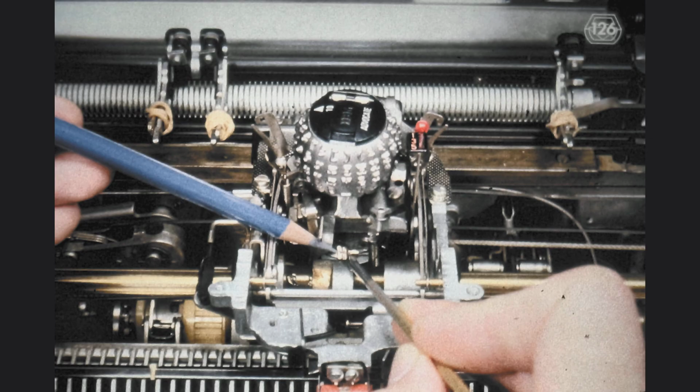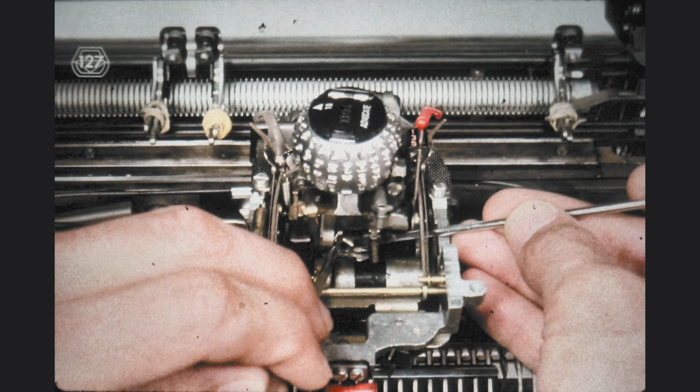With the flat end of the spring hook, you can grab and hold the T-shaped tip of the rotate tape as shown here. Holding the tape this way lets you rotate the tip into the position needed to hook it up with the rotate tape pulley. All you need in addition is a small screwdriver to push the T-shaped tip into the slot. Be very careful not to release the rotate detent by inadvertently moving the detent cam follower or the detent actuating lever. Here you can see how to handle your tools while you hook up the tape.